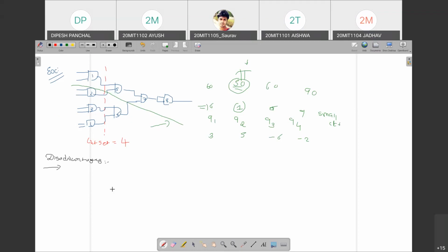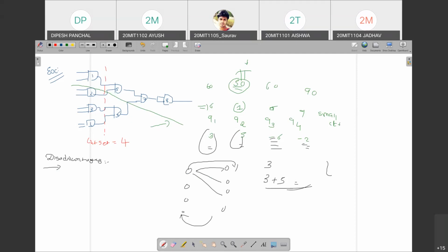Because we have to complete the procedure for each and every pair of nodes. Not for just one we get positive and we stop. There are 4 nodes here and 4 nodes here. All 4 we have to swap. This means all 4 here and all 4 there after one pass. You have to check all gain values. So in some cases you will have a positive number also, in some cases you have a negative number also. And then you have to decide where it becomes maximum like this. That only 2 times, there are 2 pairs you have to swap. That is the logic.